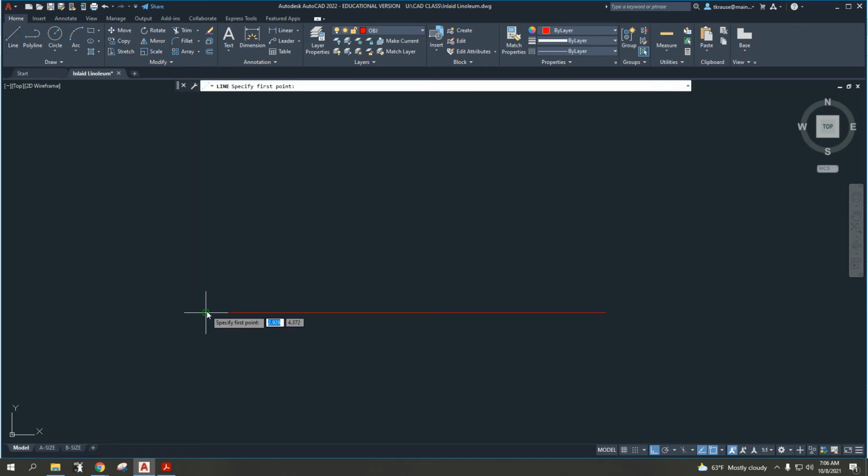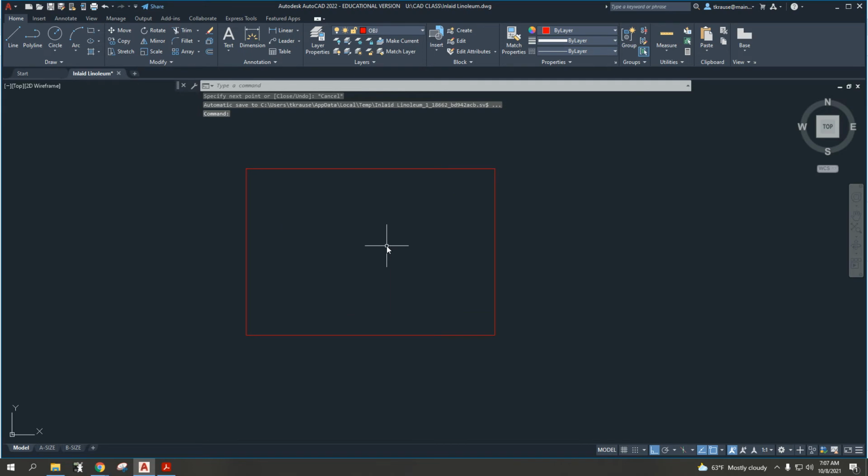We're going to go back up and get a line. I'm going to draw this time starting at either corner of the line, and I'm going to go 5.5 and hit enter. And I'll zoom out a little bit, and I'm going to do dragging my cursor in the direction I want the line to go. I'm going to type in 8. Okay, and I'm going to come down here to the end point of the other line, left click to end it, and I'm going to hit escape. And right now I should have a 5.5 by 8" square.